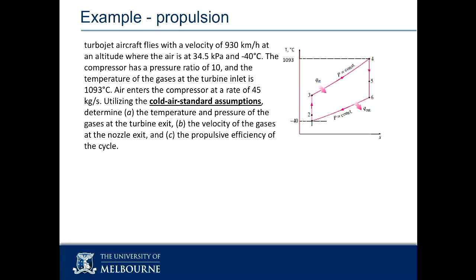If this thing times out on me before I get to the end of a diffuser, I want to make the point out loud, on record, and to your faces. The most common thing to go wrong with a kinetic energy problem is units. The units of kinetic energy get solved in joules, and almost everything else we're dealing with gets solved in kilojoules.